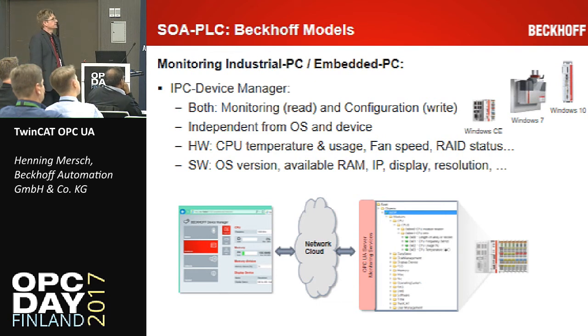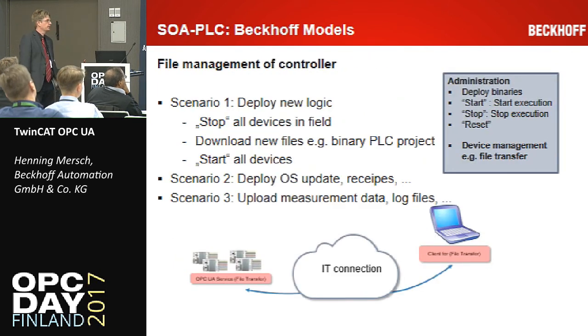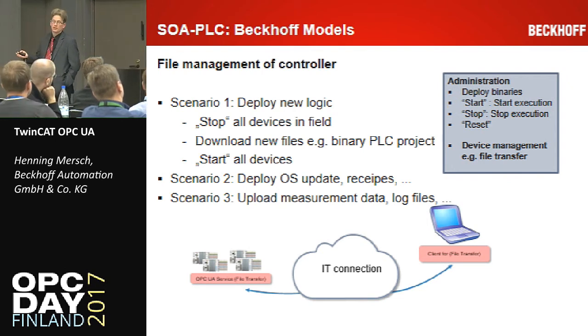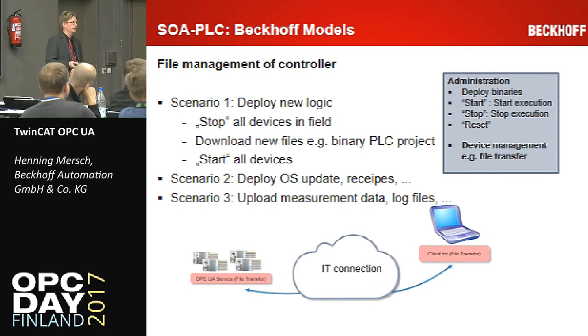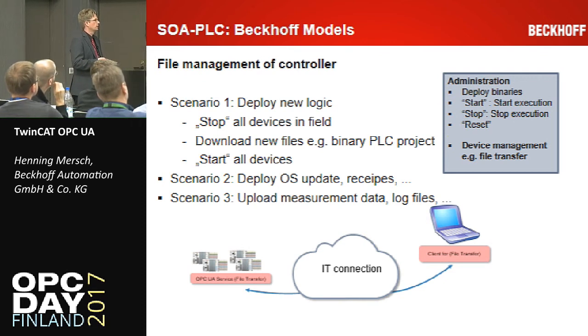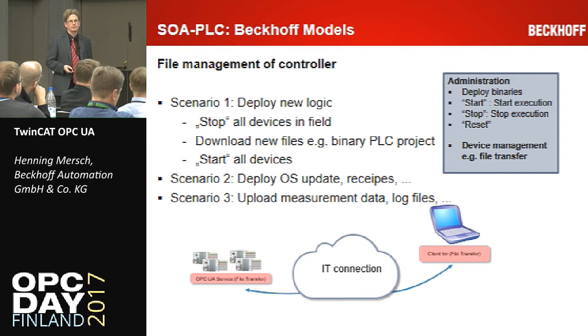The second one is that the maintenance of the PLC could be done via file transfer. File transfer itself is defined in the UA specification, and we have implemented this into our PLC, so we are able to receive and transfer files, and this functionality could be used, for example, to update the PLC code.